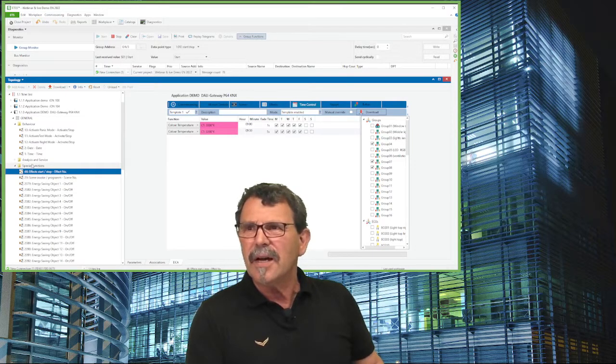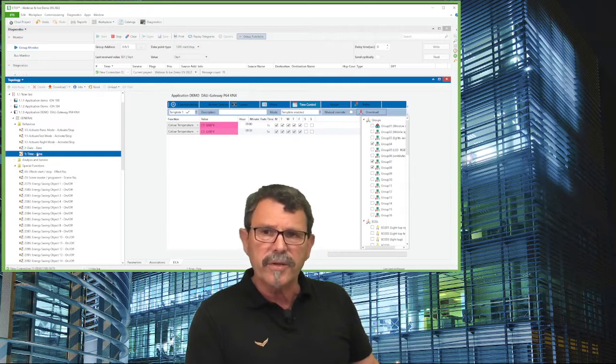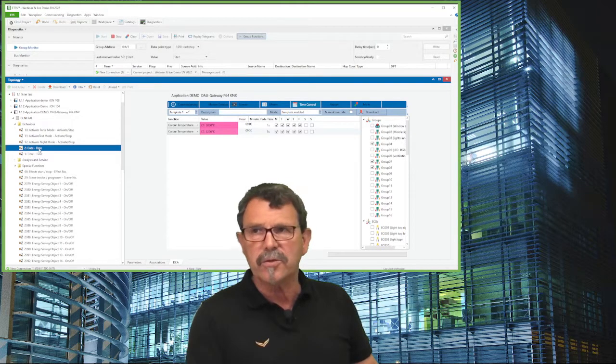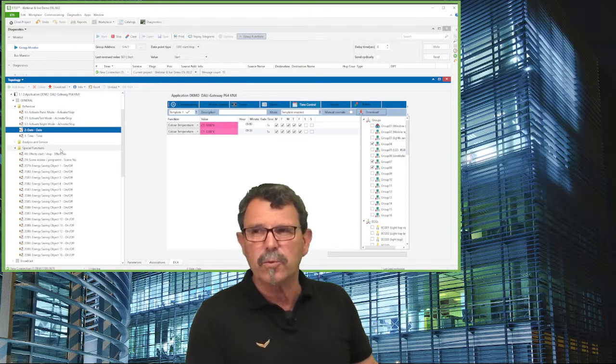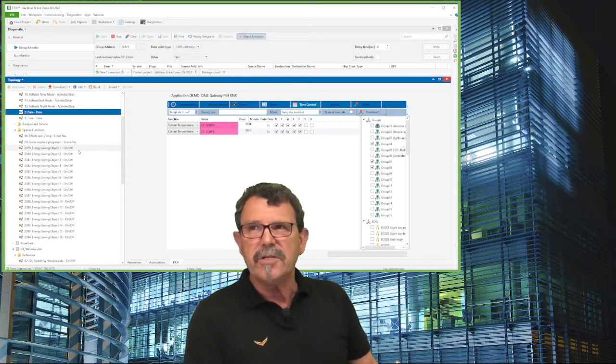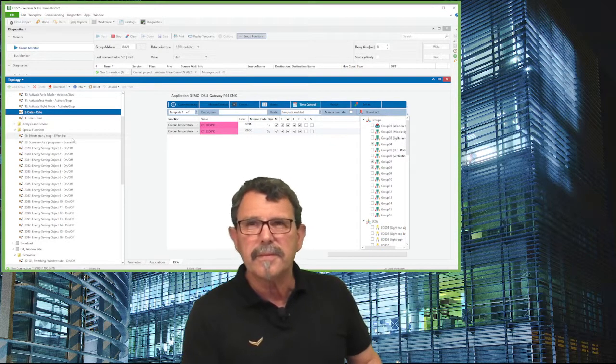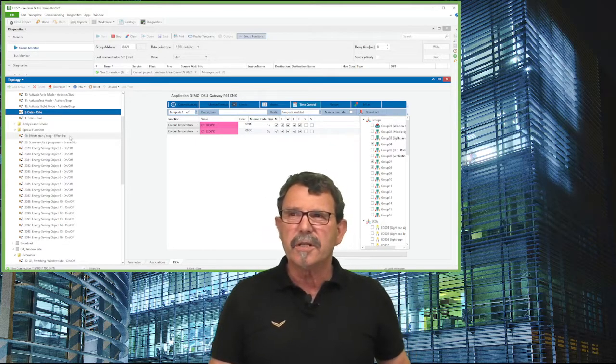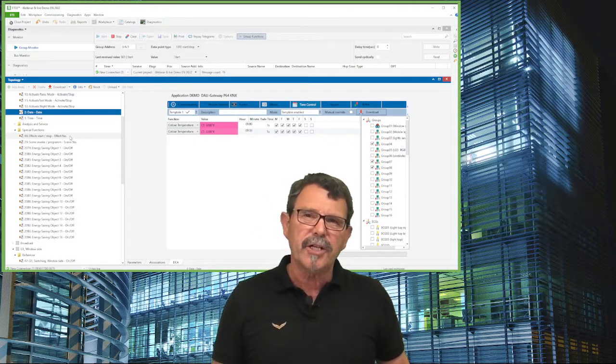behavior, and for this, we especially need to synchronize the DALI Gateway, or update the DALI Gateway, with date and time. This is important so that the controller inside knows what the current daytime is. And these effects you start by, not this effect, this time control. You start finally with this communication object